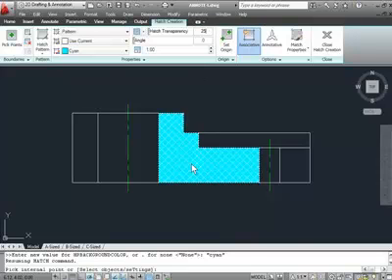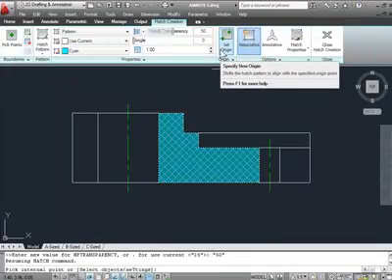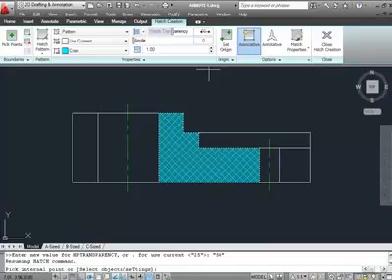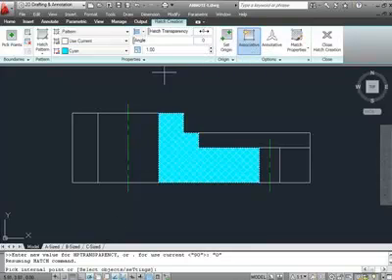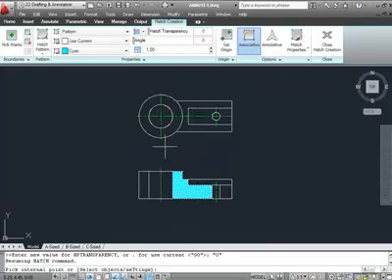Now we can set the transparency as well, so we can start to fade that so that it's not so intense, but we can still have the color and the hatching in our drawing. But they're not at full opaqueness on the drawing compared to all the rest of the objects. The highest you can go is 90. You can't go all the way to 100 simply because then it would obviously be transparent completely and it would disappear, and that would be confusing on whether or not it's set to transparent or whether or not the layer itself was turned off or frozen.